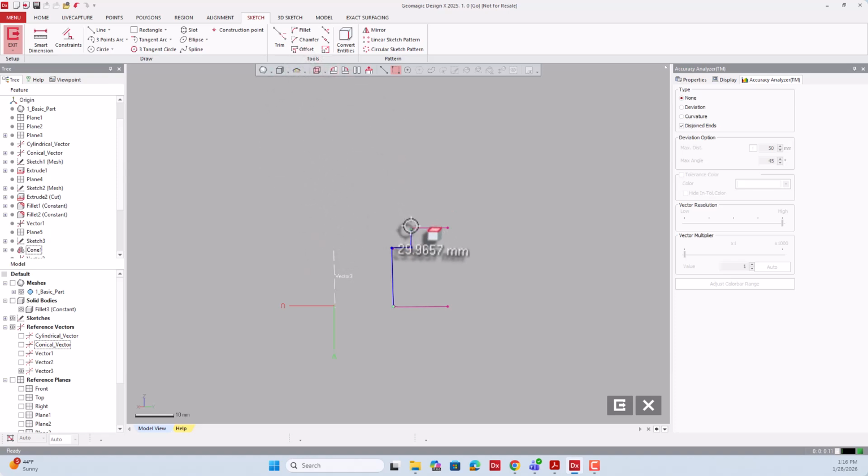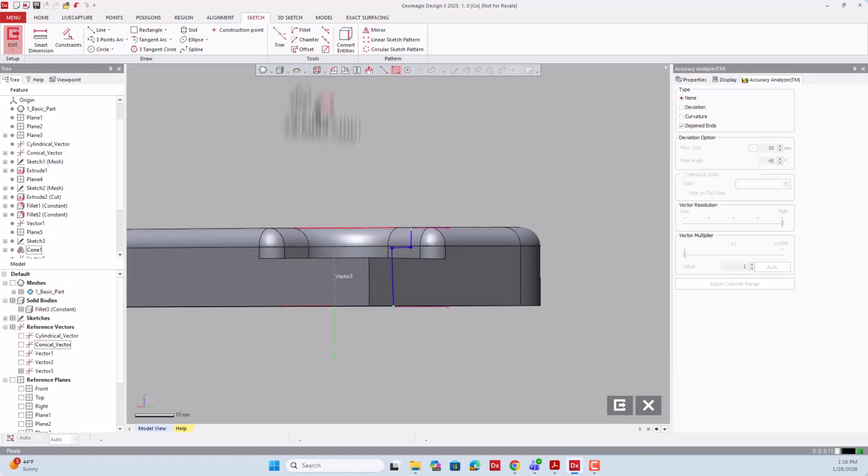And if I want to extend this beyond my solid, I can go here. Notice this is the resize tool that we used previously, so I can click on resize, and it would bring me this widget, and I can click on this vertex and drag it up like that. And when I'm done, I can say okay.